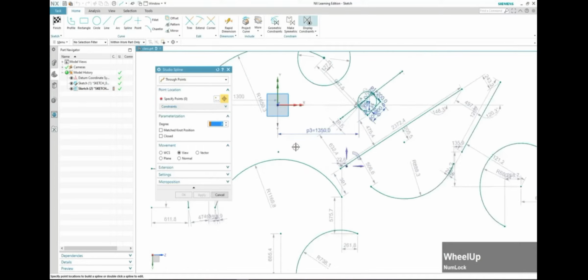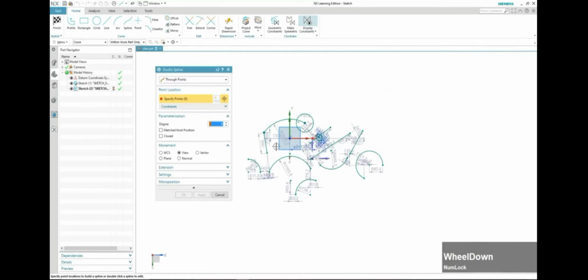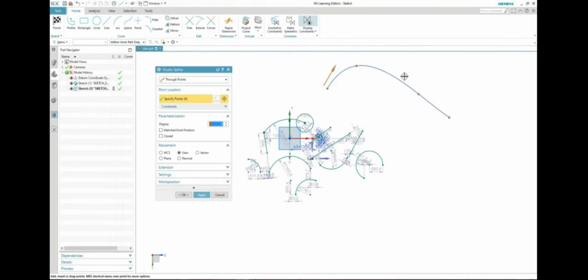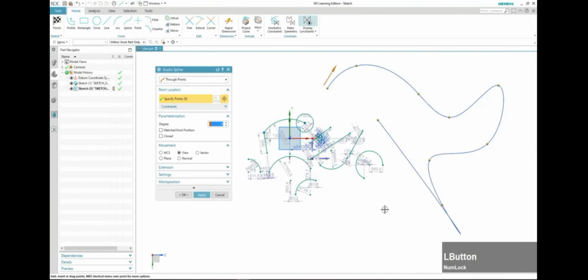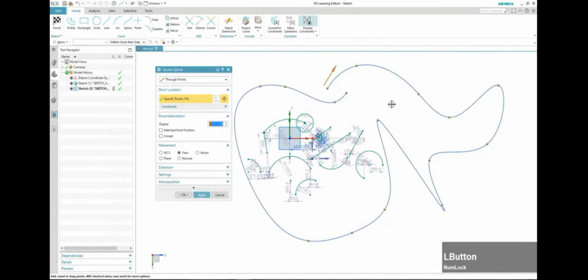Okay, next, that is spline, right? Spline is a continuous line, right, which is tangential, you can say, to the previous point. Right? 1, 2, 3, 4. You can see this point to this point is smooth. We can't say tangential at every point, right? But it tries to maintain it tangent. You just click on points, and various points will be generated.